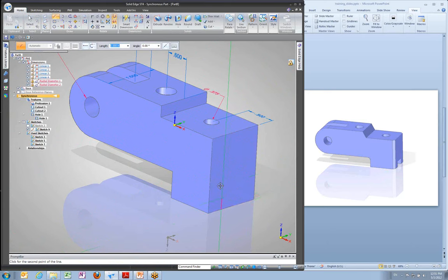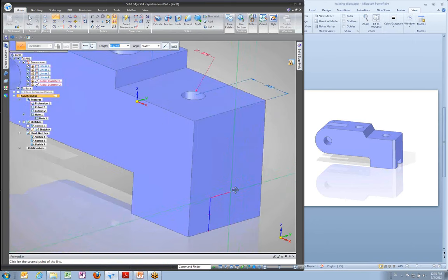Now in this case, I'm going to start drawing by selecting that bottom edge, coming out. In this case, I haven't gone into my sketch view. I'm going to let my mouse feedback and the crosshairs on my cursor tell me when I'm horizontal or vertical. And I'm going to drop that in there, and then it'll give me a region that I can click on and extrude out.